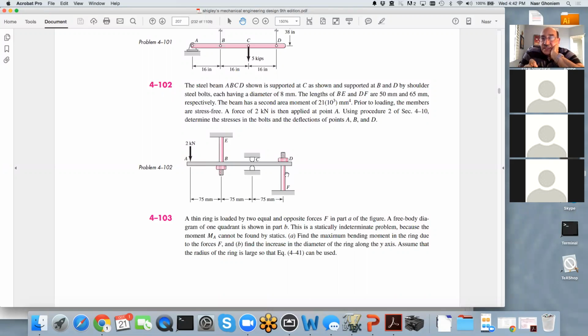That's the key point here, because we would like to determine the force reactions at EB. So there's a reaction here at C and at DE. So I have 3 unknowns and 2 equilibrium equations. Can't solve. So this is a statically indeterminate problem, as we discussed in class. So I have 3 unknowns and only 2 equations. Therefore, I must go to the idea of deflection. So when I have deflection, I have to find a deflection equation, as we discussed.